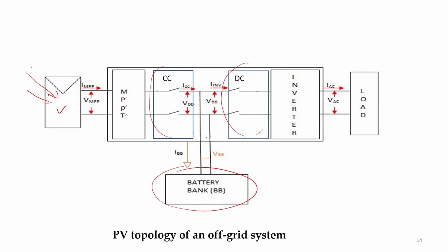If we need to meet the demand at night or off peak hours, then we have to store and we can use it. And again, if we have DC load, then directly you can go to the load, and if you have AC load, then this has to pass through inverter, right. Sometimes these MPPTs are not installed, but it is assumed that here MPPT is installed and these components are actually not staged together always.